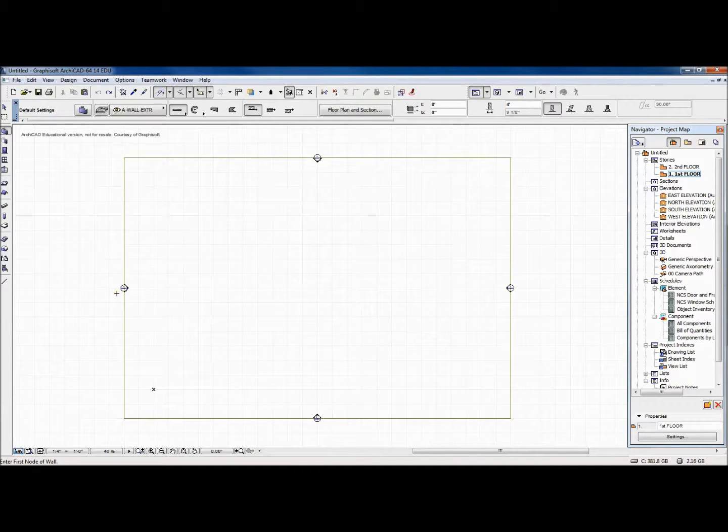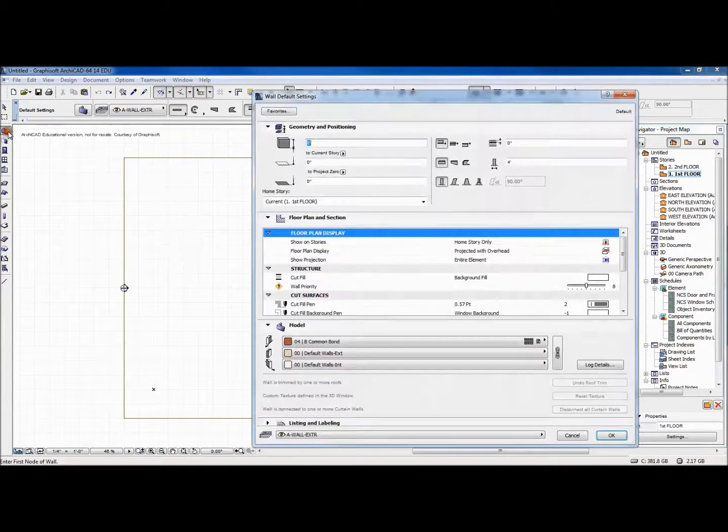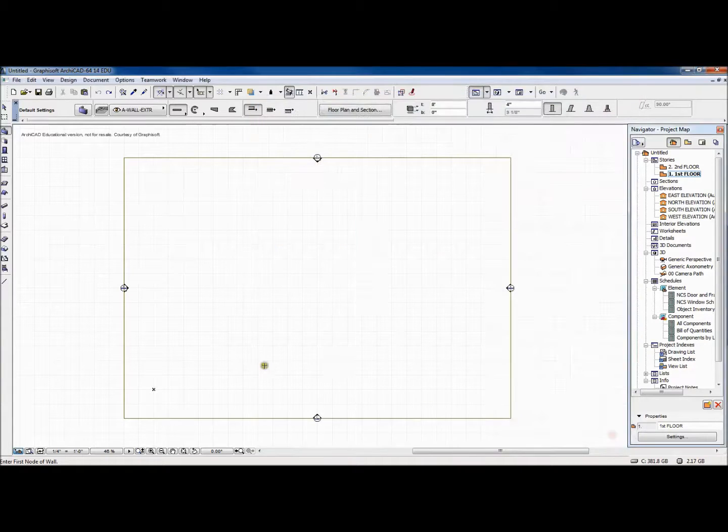This video is about how to build roofs, and so the first thing that I will do is put some walls in, and the walls are set at 8 feet. I don't want them 4 feet wide, I want them 4 inches wide, and so I will click OK, and we're going to simply build a roof on a building, and let's go ahead and make the building 60 feet